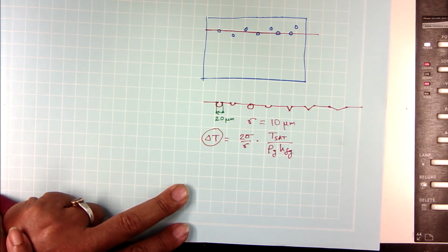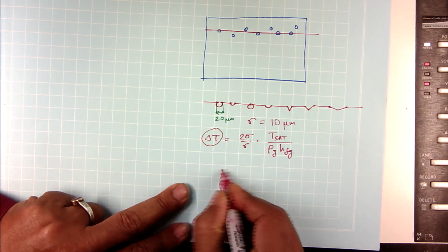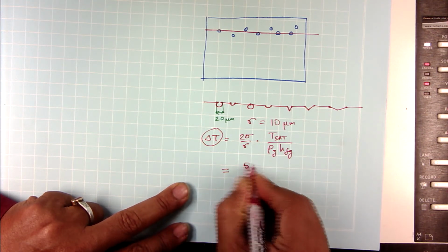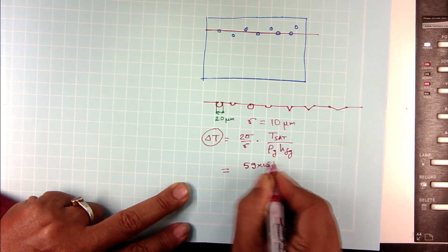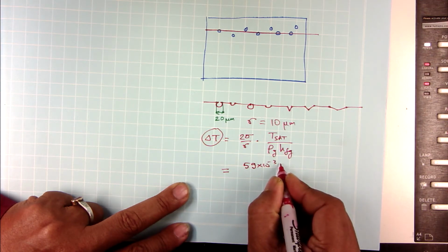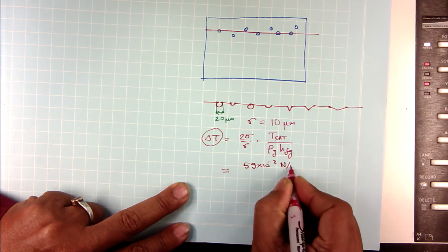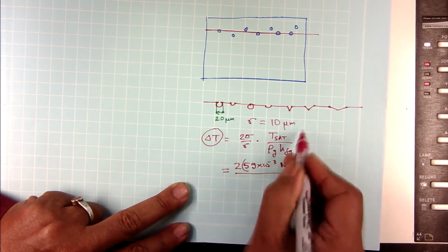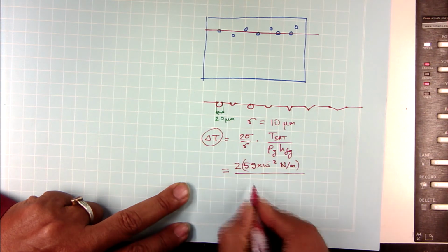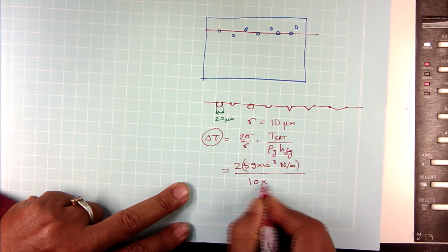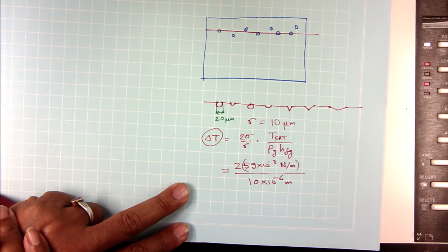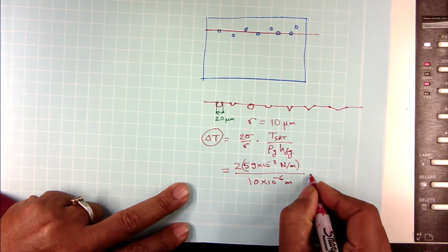Okay. So, let us substitute. So, your typical sigma for water is about 59 times 10 to the power minus 3 newtons per meter times 2. I said the radius of the bubble is 10 micron, the cavity is 10 microns. So, that is 10 times 10 to the power minus 6 meters, right. I am at 1 atmosphere pressure.